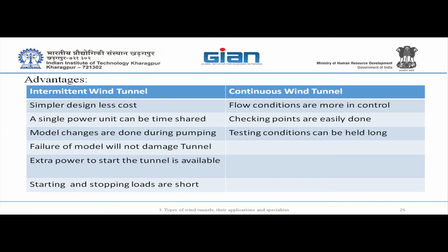So, for instance, in order to run Mach 1, what is the pressure ratio between the settling chamber and your test section or back pressure? Around 2. You need twice the back pressure in order to run Mach 1. So it means 2 atmospheres, 30 psi, that will be enough to start the tunnel. But you can run at much higher pressure to start with.